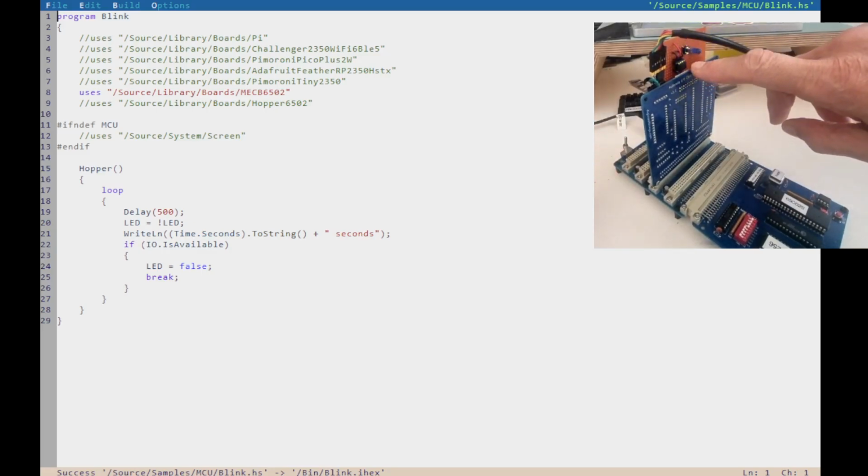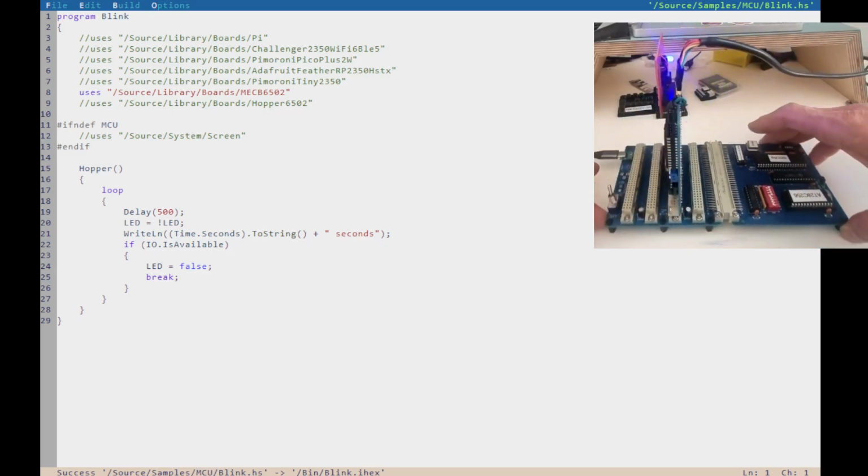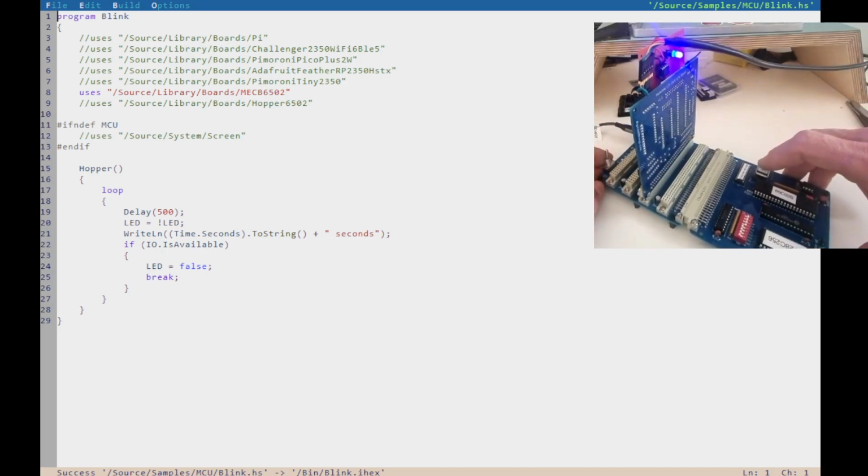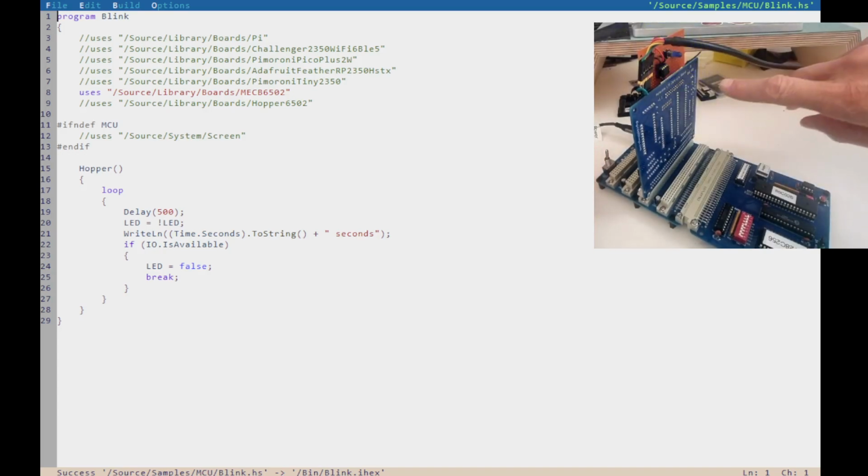little serial EEPROM. What we've got is a little I2C interface coming out of the parallel port here and being used for my LED. I've got a user button there, and it's like a boot button for the opposite of what a boot button does on an RP2040 microcontroller. If you hold it down while you boot, it won't automatically load the program, in case you've got a program loaded that's causing your machine to hang on startup. So you can unbrick it with the button.